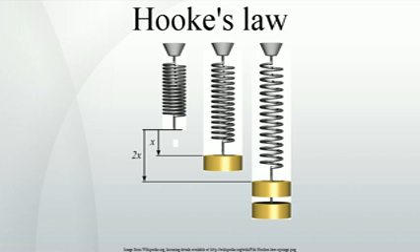For continuous media, each element of the stress tensor is a force divided by an area. It is therefore measured in units of pressure, namely pascals, Pa, or newton per meter squared, or kilogram per meter second squared. The elements of the strain tensor are dimensionless, displacements divided by distances. Therefore the entries of the stiffness tensor are also expressed in units of pressure.